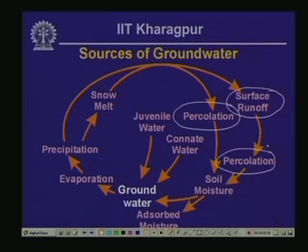A part of the soil moisture is going to be available in the form of groundwater, and another part is going to be locked within the matrix in the form of adsorbed moisture, which is tightly held by chemical bonds on the surfaces of the soil particles, and another part is going to be unavailable for use because it is going to be trapped within non-interconnected soil voids, as we are going to see in the next little bit. There are two other sources of groundwater. We need to consider those two sources as well in order to complete this discussion.